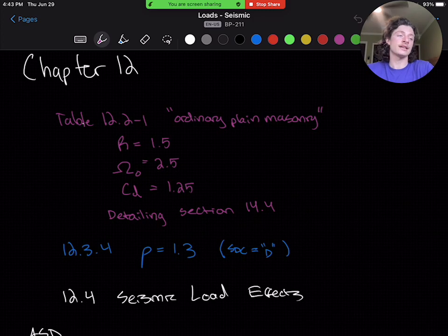So this simplified analysis that I'm going to go through is to calculate the seismic base shear on the abutments, and just the abutments. However, in an active seismic zone where seismic loading is a concern, the cables potentially could actually amplify the force on the abutments and should be modeled with the entire structure. So this analysis will also ignore the drift and P delta effects, so effects of increased loading, increased moment because of deflection or drift of the structure, amplifications due to any torsional irregularity, and more.